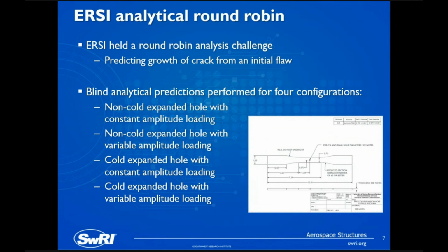And you can see there were 4 different conditions that were tested. Non-cold expanded holes with constant amplitude loading. That's kind of our baseline simple analysis to verify that everybody's running the problem correctly. And then we add the one complication of variable amplitude loading. Then we go back to constant amplitude loading, but with the cold expanded hole with the residual stresses. And then finally, we get to the most complicated and realistic problem of the cold expanded hole with variable amplitude loading.